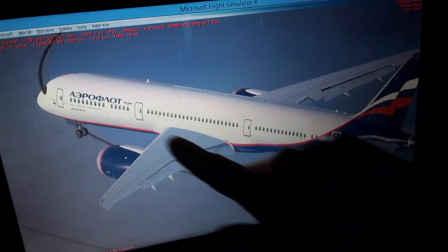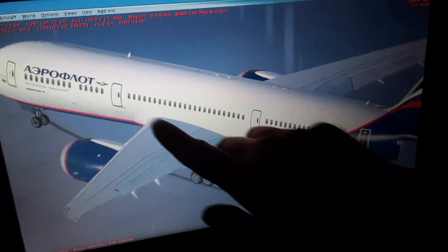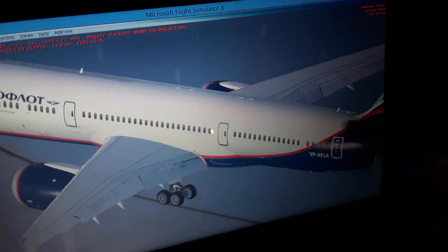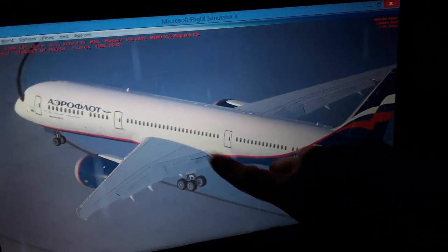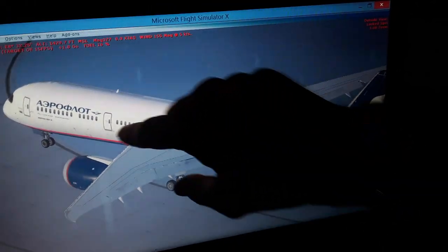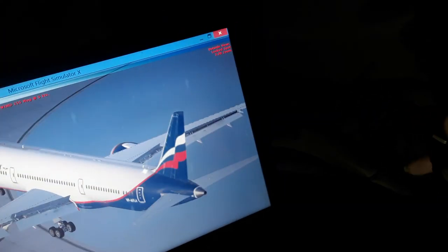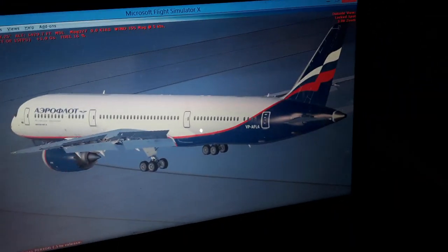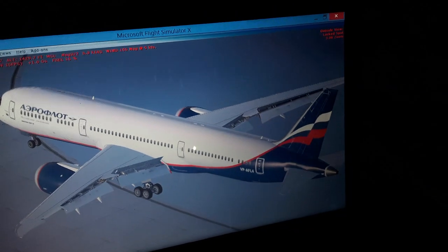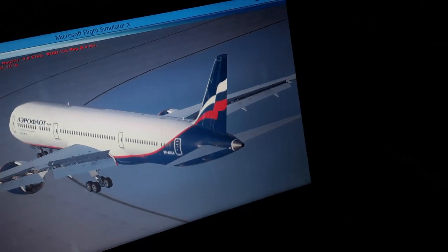Also the top surface of the wings, you can see it is more curved, so we have higher airspeed above the wings, the airflow moving much faster using the Bernoulli theory of fluids. So we have lower air pressure, which sucks the aircraft weight and wings up into the air. So this creates the aerodynamic difference, the differential pressure, higher pressure below the wings and lower pressure above, and the aerodynamic lift of the aircraft.